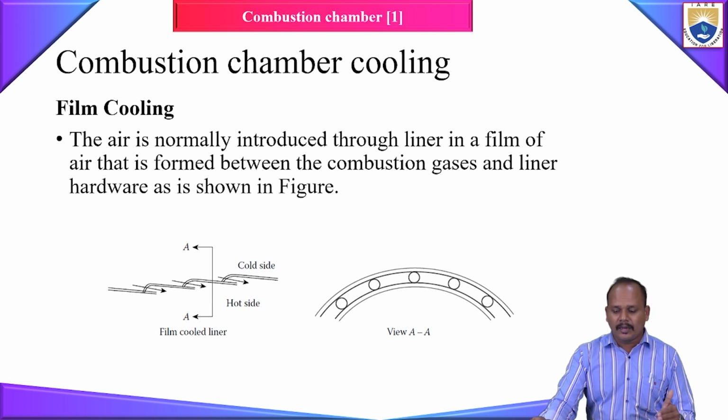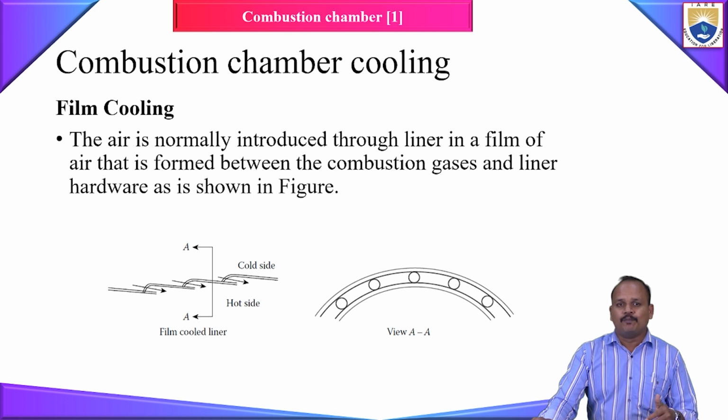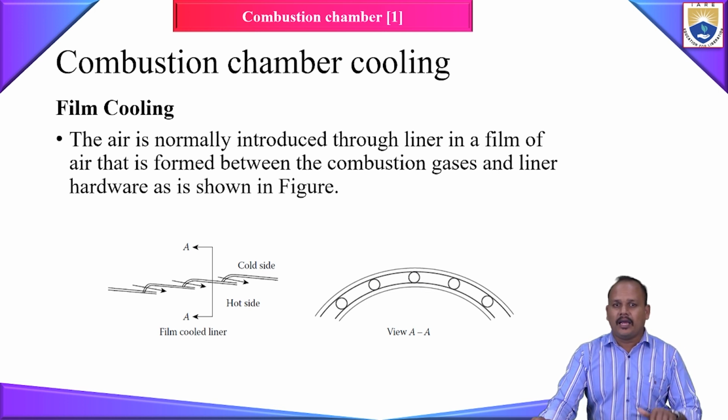So what is going to happen is that first of all, they are preventing the direct contact between your hot gas and your liner. That itself is going to reduce the heat generated on your liner. And one more thing is that as the thin layer of film cooling air continues to move, the temperature of your film also will not increase to a very high value.